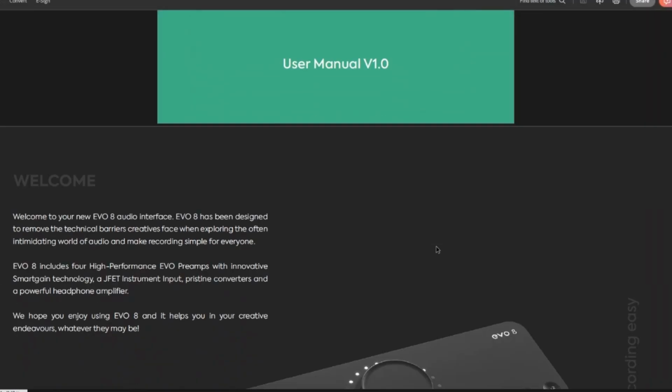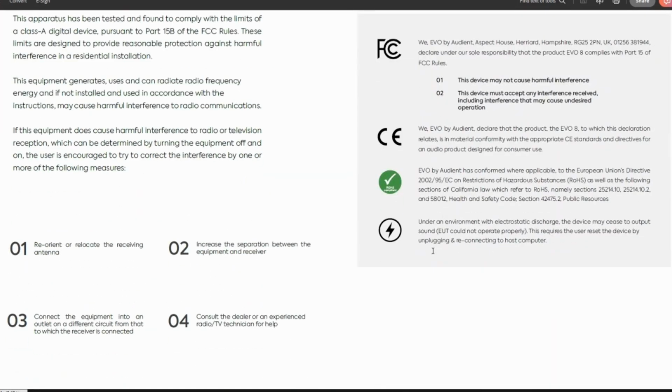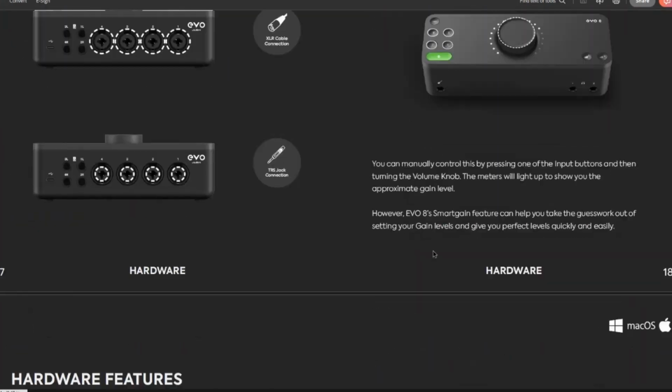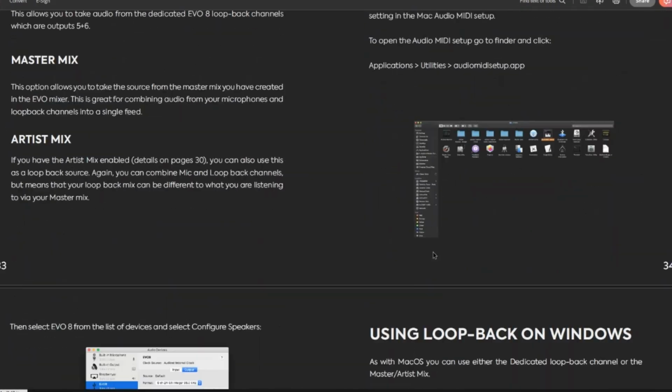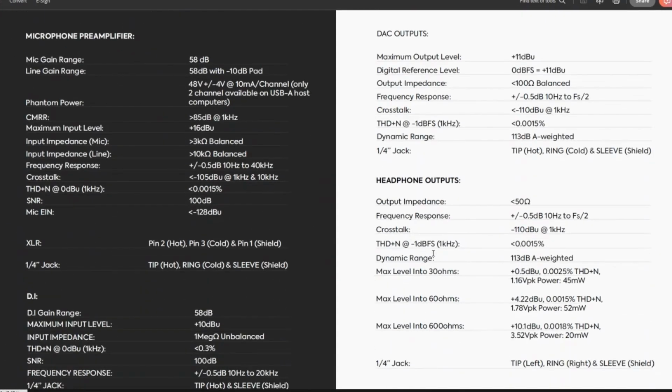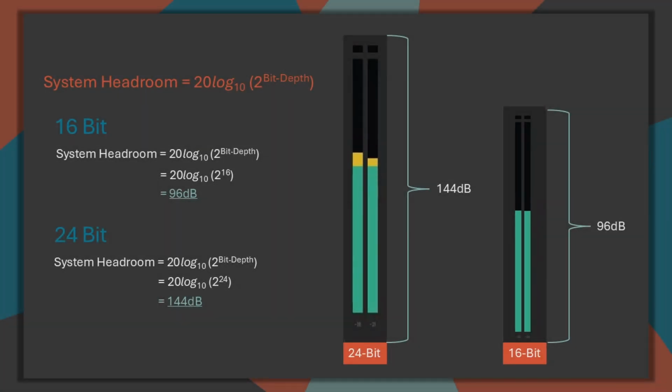Audio interfaces have input gain to consider when talking about calibration. This specification can usually be found on the manufacturer's spec sheet and is measured in dBu for the input gain. This is how much system headroom the input has before it clips or distorts. The USB audio interface I am using is the Audient Evo 8, and it has an input gain of 16 dBu.